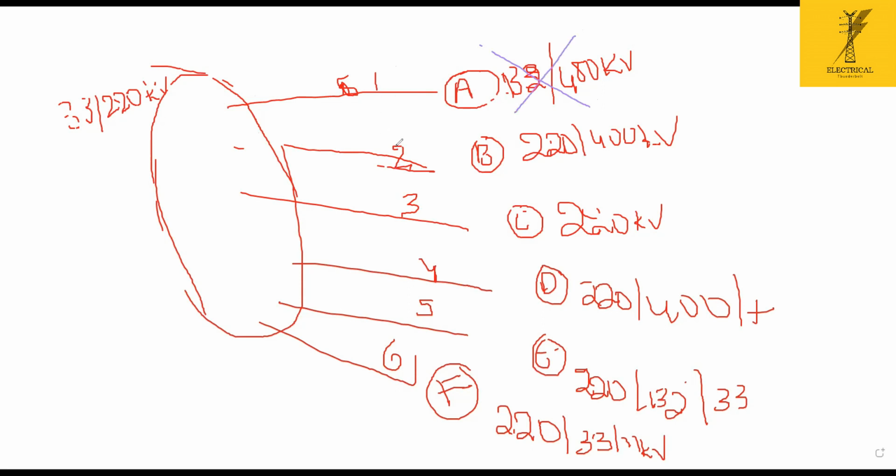Then I am moving to the next, second substation. I went here and I find there 220 kV is there. But here what I noticed is the 220 by 400 kV, where the existing 220 kV is stepping up to 400 kV, the transformer capacities are already highly loaded. The transformer is only 300 MVA. Out of 300, already 200 MVA is loaded. Only 100 MVA is left. But our project is 200 MVA. So the transformer loading issue is there. You cannot export 220 to 400 if you connect here.